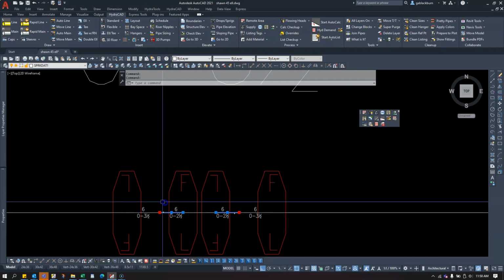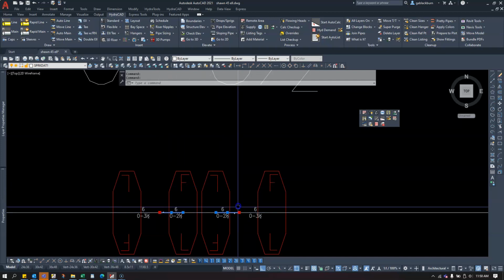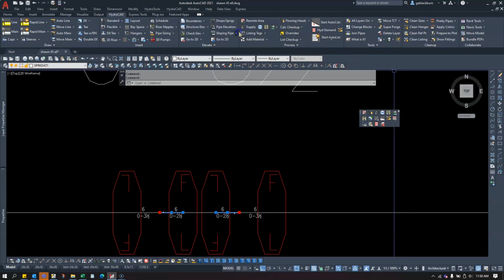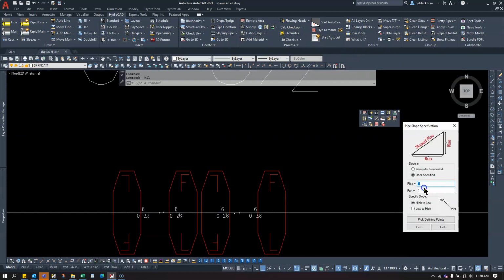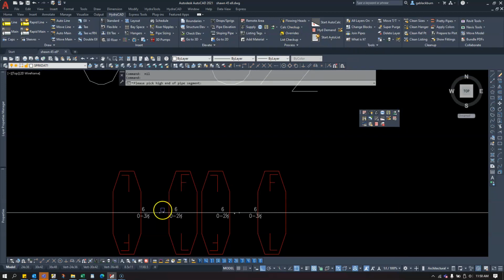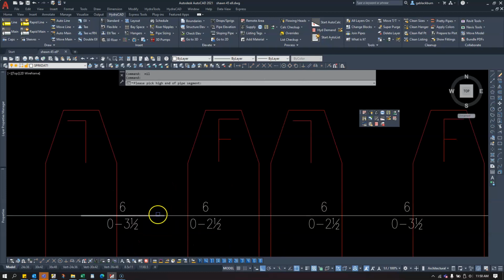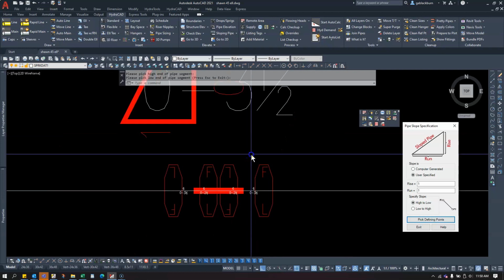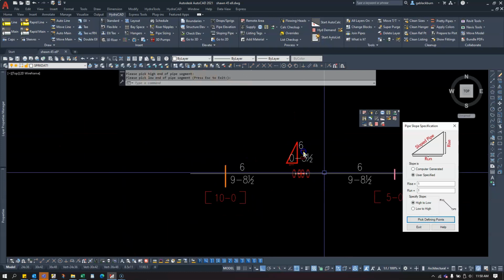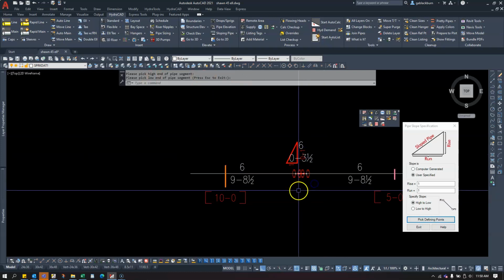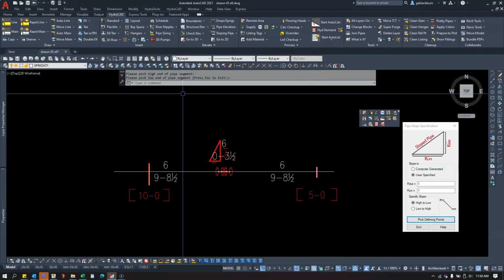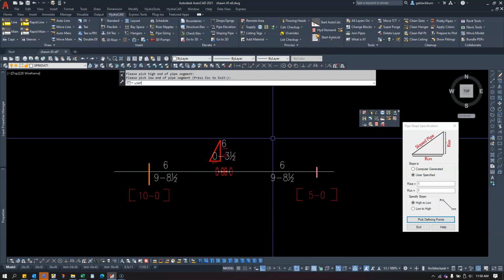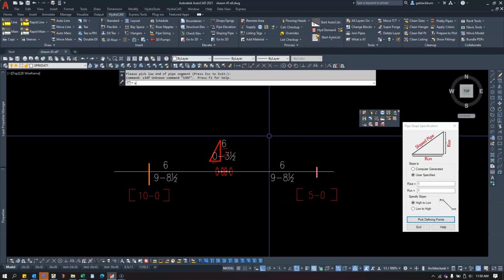So basically from the middle of the 45 here to the middle of the 45 here is where we're going to show our new sloping pipe. 1/1, pick defining points from, and I'm going to go from here to there. All right, looks good. So now I have that pitch showing the 45, and now that everything's all set, I will show 3D, and I have to type properly, show 3D, enter.